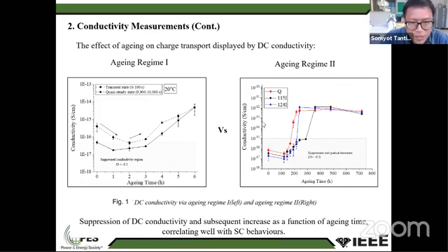Yeah, maybe, but the aging process has already started in the polyethylene material, and when it reaches the aging threshold, the conductivity will increase significantly and progressively to some level, and will be saturated at some point of the aging time. This is a remark for the conductivity change with the aging time.